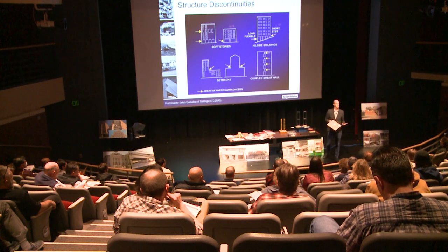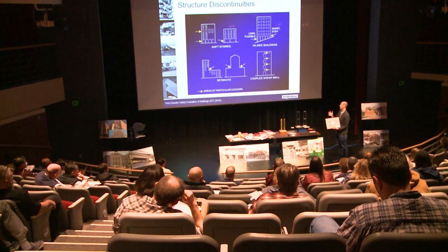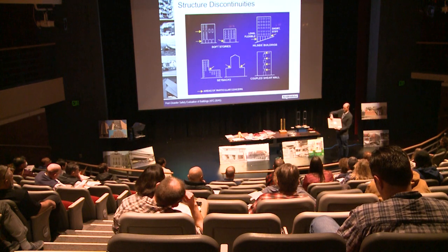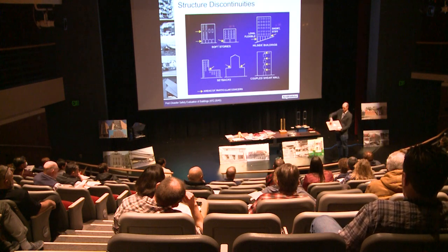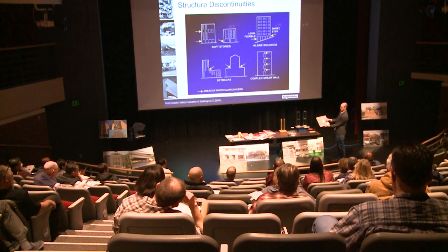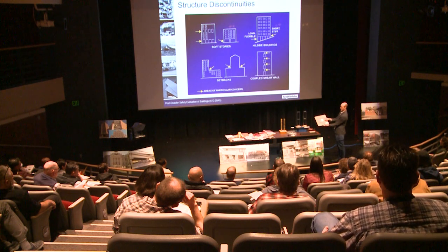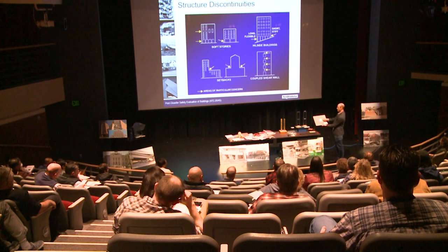A way to explain this, or an example, would be, if this is a concrete shear wall building, this more flexible spring would be a 10-foot long shear wall, and the stiffer one would be a 20-foot long shear wall. And so if an earthquake is shaking, this stiffer one is taking more than its fair share of load, particularly for a rigid diaphragm building, which is all to say a concrete floor and concrete roof type of building.